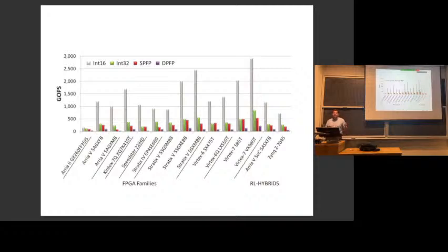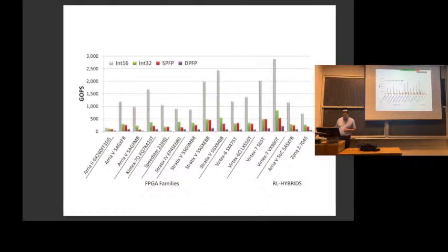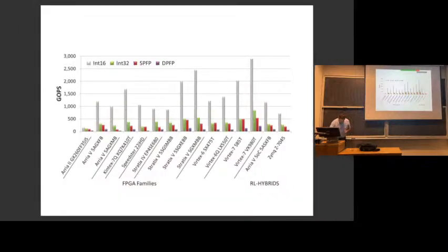So if you build a 16-bit multiplier, we're going to actually see how to build these a little later because we'll look at the DSP blocks. But basically, the amount of logic you need to build a multiplier grows with the square of the multiplier width, OK? And you'll see that later in the course. We'll go through that in a little more detail. So basically, FPGAs can build a lot more small operands than they can big ones because it doesn't take as much logic. It also doesn't take as many DSP blocks, but that might be less obvious until we look at their architecture. So that's why they do better with 16-bit integer than 32-bit, and it's actually more than 2x.